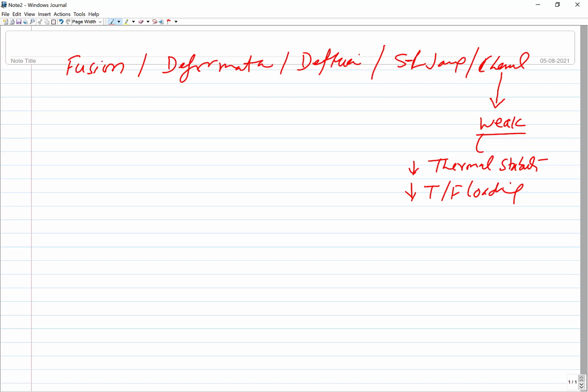If the joint is non-load carrying type, it has to be used under dry ambient conditions, and the temperature is also not high, like say 40-50 is fine. Under those conditions, where the role of the joint is just to ensure the proper placement or positioning of the two members being joined, it is fine to use the adhesive joint. But these are not good for high load carrying capacity, and the primary reason behind this is the absence of metallurgical continuity in the joints.